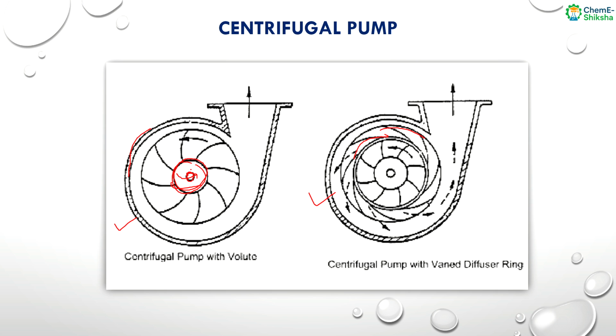Now when this fluid comes out of this impeller blade, it has some kinetic energy because the impeller blade imparts some amount of kinetic energy on the fluid. So the kinetic energy of the fluid will increase. Also at the same time there is a change in the static pressure while it flows through the impeller blade, because the impeller blade is diverging in nature. In the direction of flow, its area is increasing.